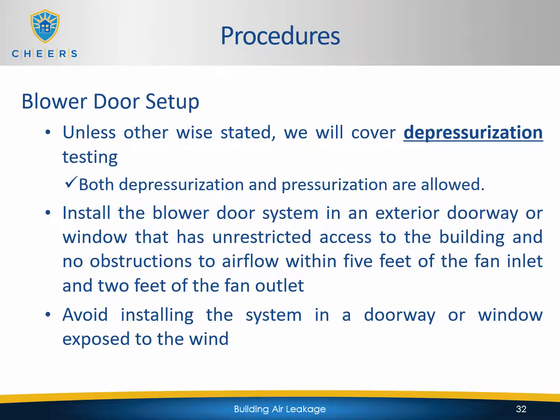As far as the setup is concerned, unless otherwise stated, we will cover depressurization testing. Depressurization testing is the primary method to test for the blower door, and those are the standards that we use in California according to the reference appendices. So again, unless otherwise stated, we will cover depressurization testing. You'll be sucking air out of the house.